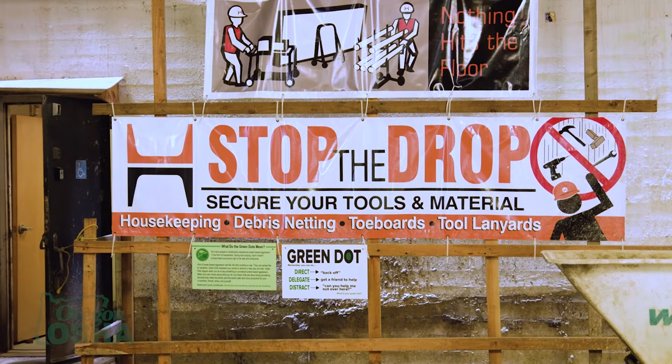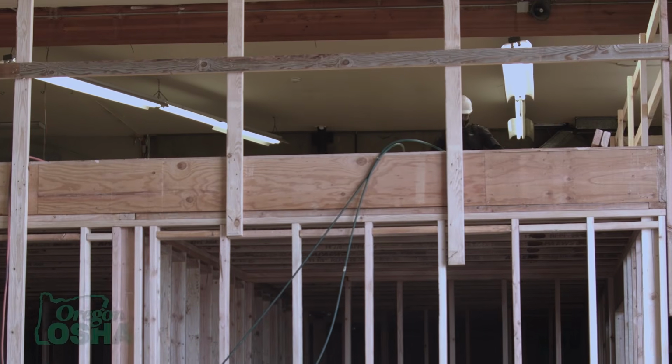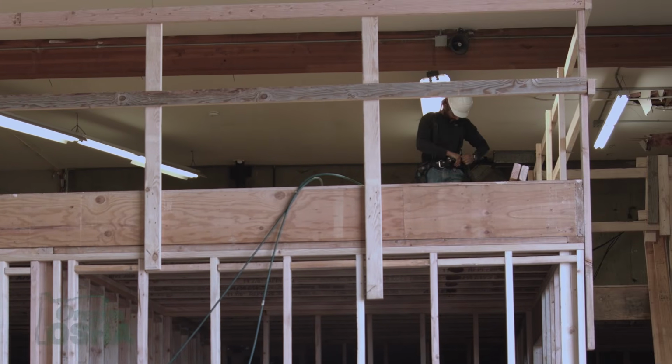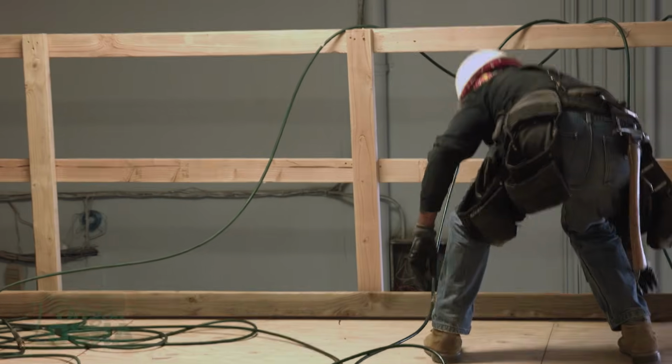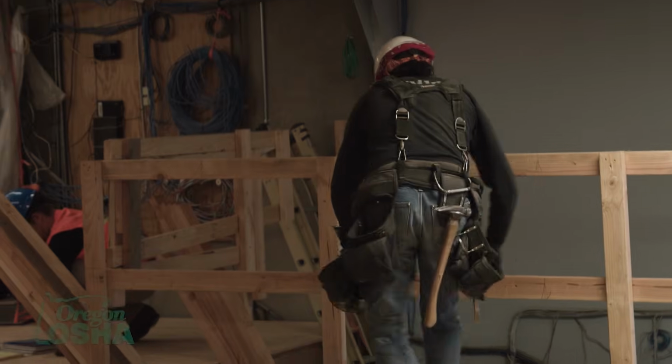So there's several ways that an employer can protect their employees from falling object hazards. The first one is eliminate the hazard altogether by not allowing employees to be underneath areas where materials can fall from above. As long as there's no employees underneath, there is no exposure to a hazard and you don't have to worry about it. But if employees do need to work underneath, then we want to take into consideration things like, if you're using a guardrail system above to prevent employees from falling to a lower level, that we have toe boards installed to prevent tools from accidentally being kicked over the edge.